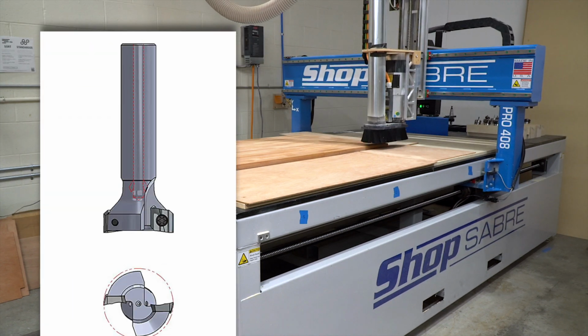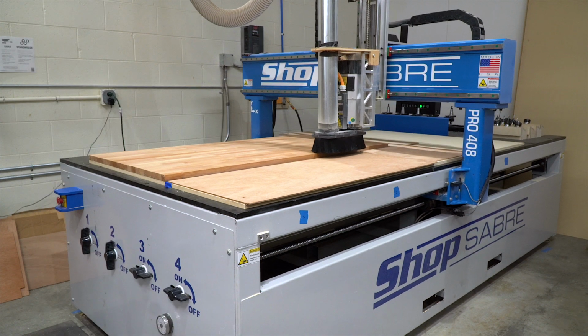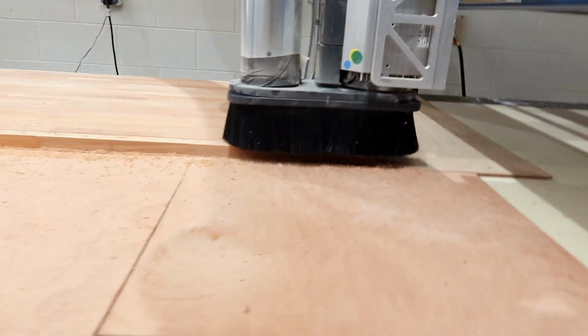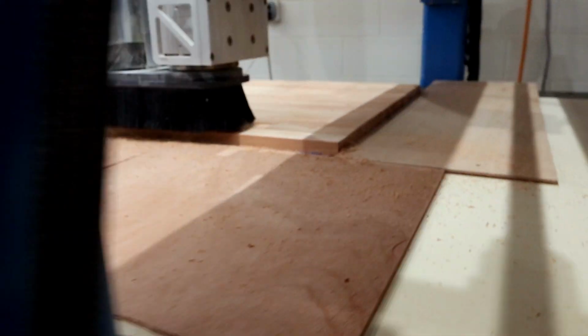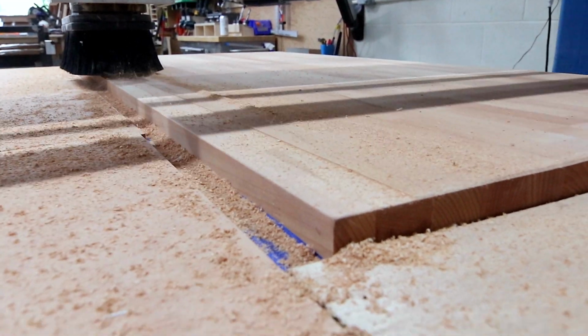First up here is the shear hog to face the top to get it nice and flat. If you're wondering how we're workholding this, we have a vacuum flow-through table, so there's a big vacuum in the back room and it pulls through the top of the table, through the MDF, to our workpiece here.